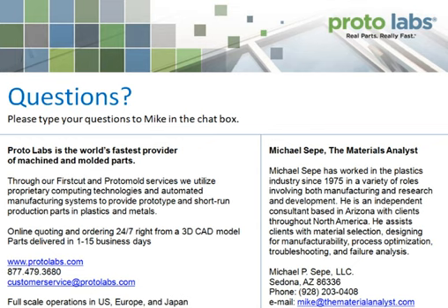If you haven't, then your colorant supplier is doing a very, very good job, because they have to be aware of the fact that these colorant systems are going to be exposed, if only briefly, to temperatures many times upwards of 700 degrees Fahrenheit. And not every colorant system can do that. And if the colorant system cannot survive the molding process, then it's not something that you can use. So difficulty in processing very often is defined in terms of, how well does the color survive the molding conditions, and that's what I'm referring to.